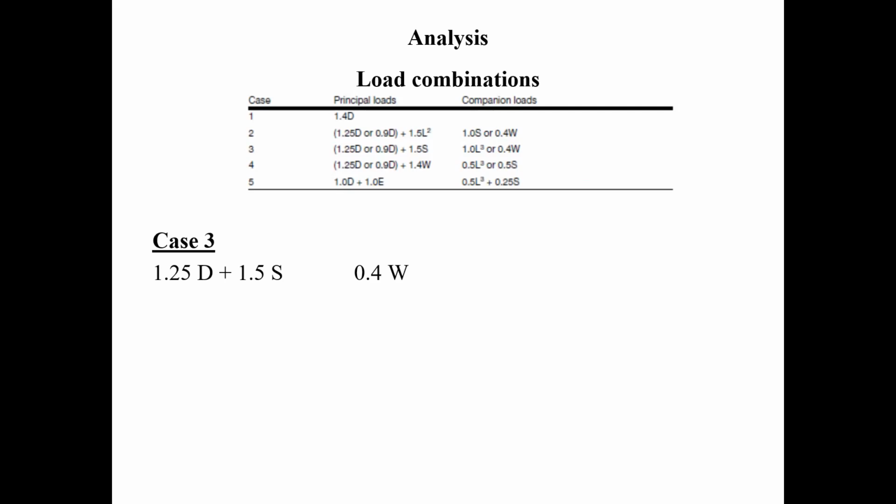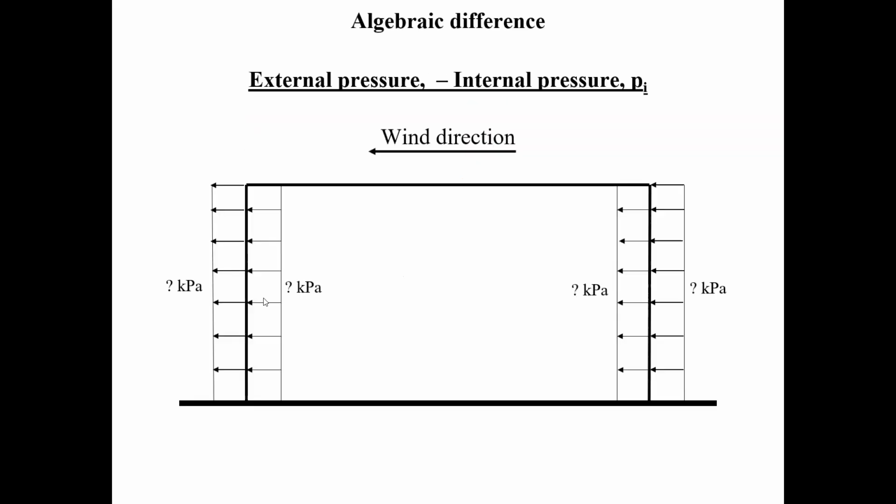And that's going to give you your W here. This is your W here, and this is your W here. You take the higher of the two. Whatever these two are and whatever these two are, you take the higher and that becomes your W. My spacing is 0.6 meters. Therefore, my WF becomes whatever value I have here multiplied by 0.6. Sir, what happens if both of them are the same? Then it's perfect. That means you can take either one to do your design.